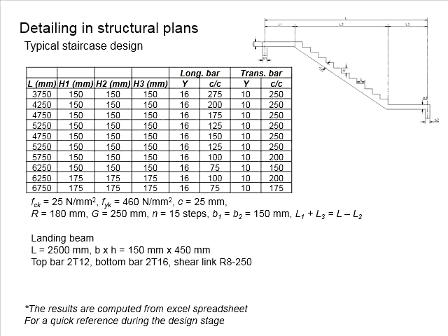It will be good of you if you really try to work out the table, and you just need to do a one-time job. Design accordingly. Use the spreadsheet to generate all the possibilities, and then next time when you encounter the design for the staircase, you may straight away adopt the amount of reinforcement bar.